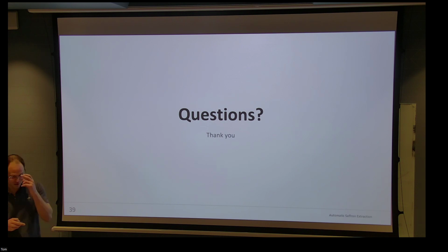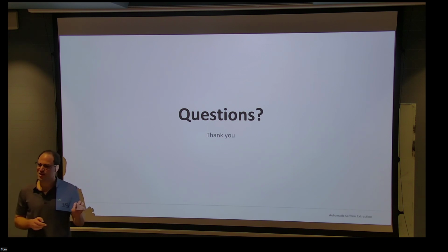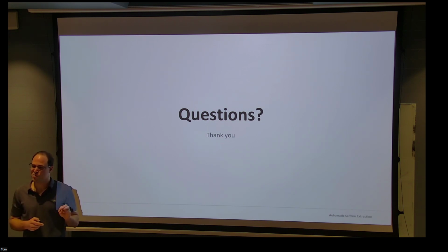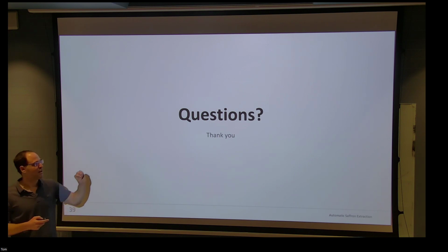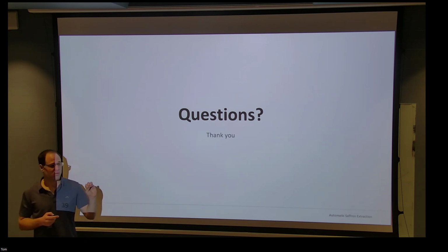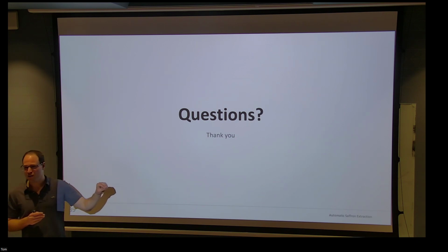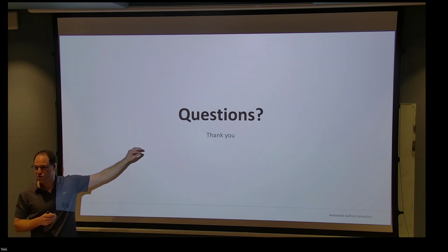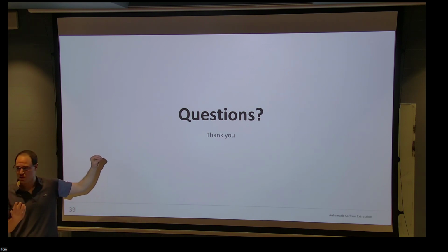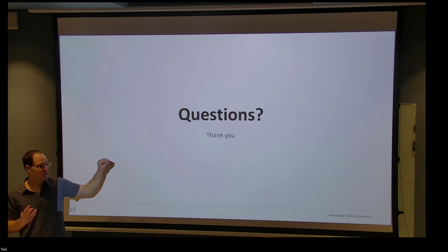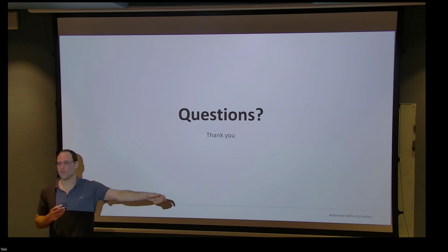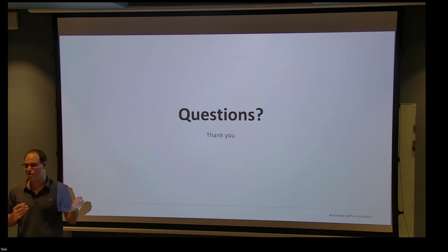Maybe, yeah. Okay, you mean the camera on the robot? That the camera is moving. We considered at the beginning to move the camera, and we talked about putting a simple camera on the robot arm. That is the more traditional way to make picking. And we saw that if we make a good calibration and good assumptions and a good algorithm, we don't have to. Now the robot goes without seeing anything. It just goes to the point and it works.